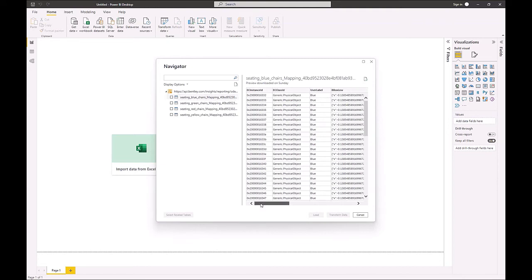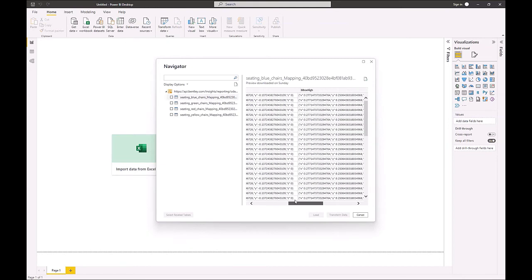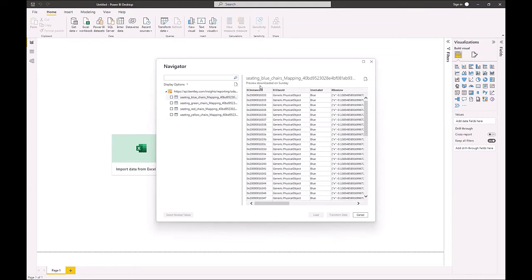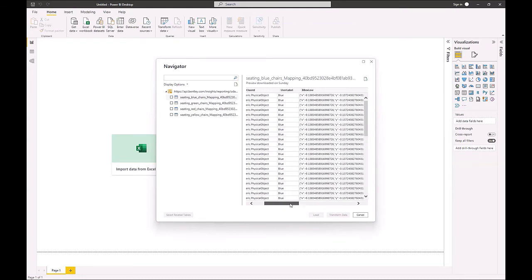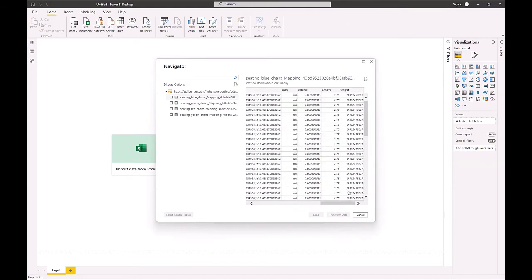Over here, this is all the data that was exported from the iModel. There are 5 hard-coded columns that are always provided: EC instance ID, EC class ID, user label, bounding box low, and bounding box high. And there are the 4 properties that I added myself to be extracted. You notice that color is null. That's because it's redundant with user label. But the interesting ones, the cool ones, are volume, density, and weight.